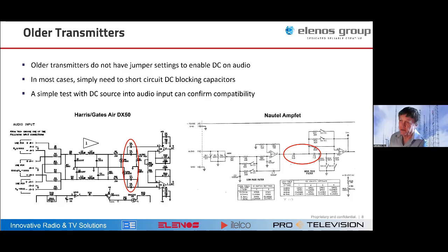If you can't dynamically pull the carrier down, that would be a problem, probably. Well, they were doing testing to see how far they could reduce it, because they do use it in the receiver. And I think the answer was 3 dB is fine. That probably will go forward, that we'll just decide that we can reduce that carrier by 3 dB. And then around 6 dB, they started to see some negative effects on reception.